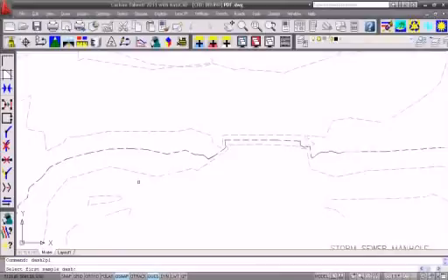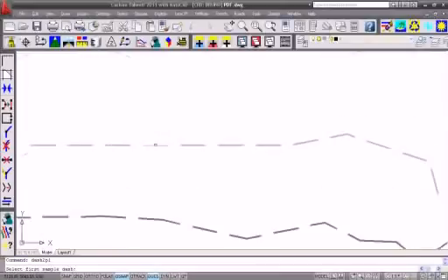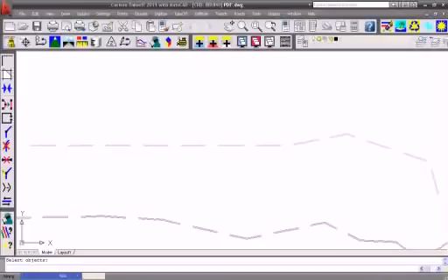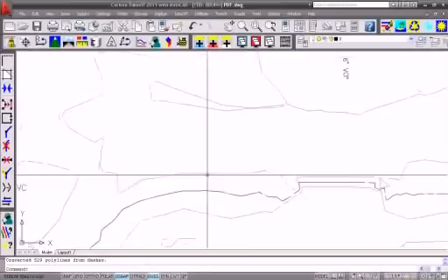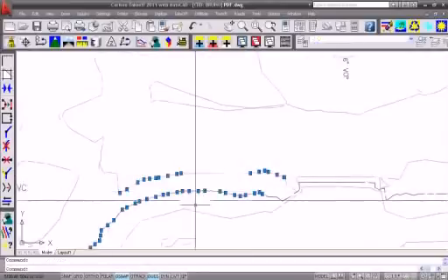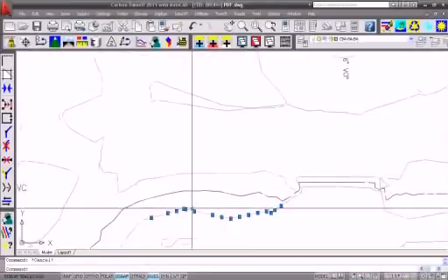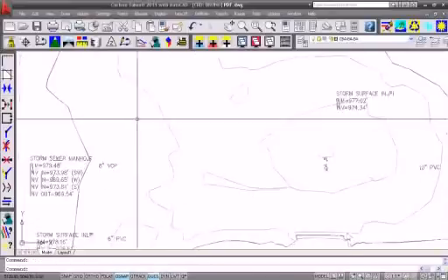It asks me for a sample of the dash. So let's zoom in here. Select an adjacent dash line. This is so the program can approximate the gap between the line work, so it knows how to join it. And it says what to process, and I'll type in all, enter. And now I get solid lines on a lot of that line work.